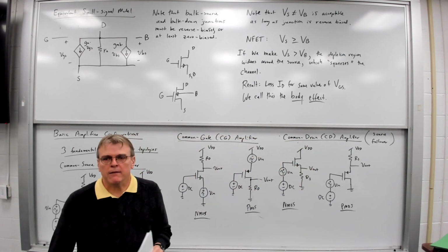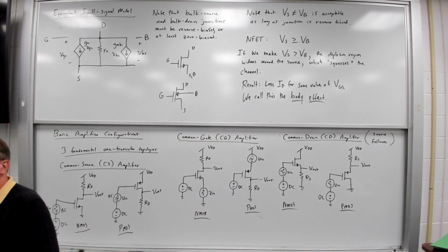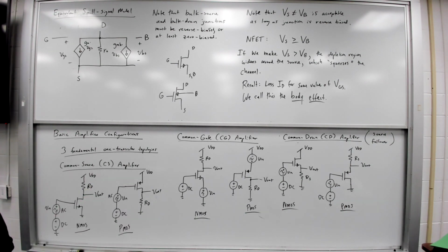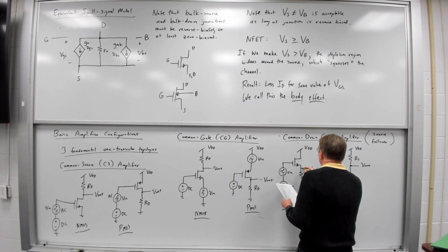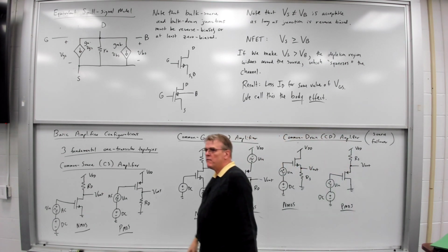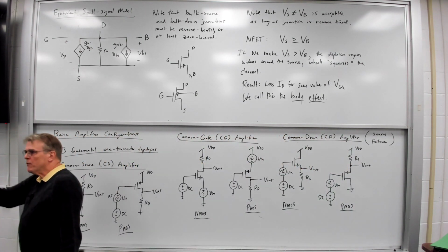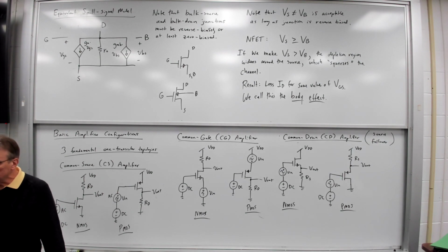And so here we're taking the output not at the drain, but at the source. But the input is still at the gate. These are our three fundamental transistor topologies. They differ either in where we're injecting the input or where we're taking the output.